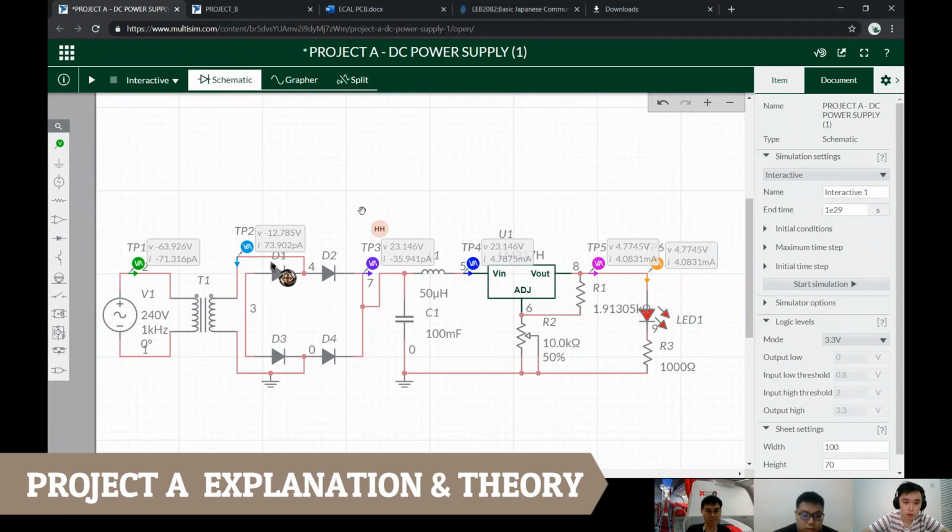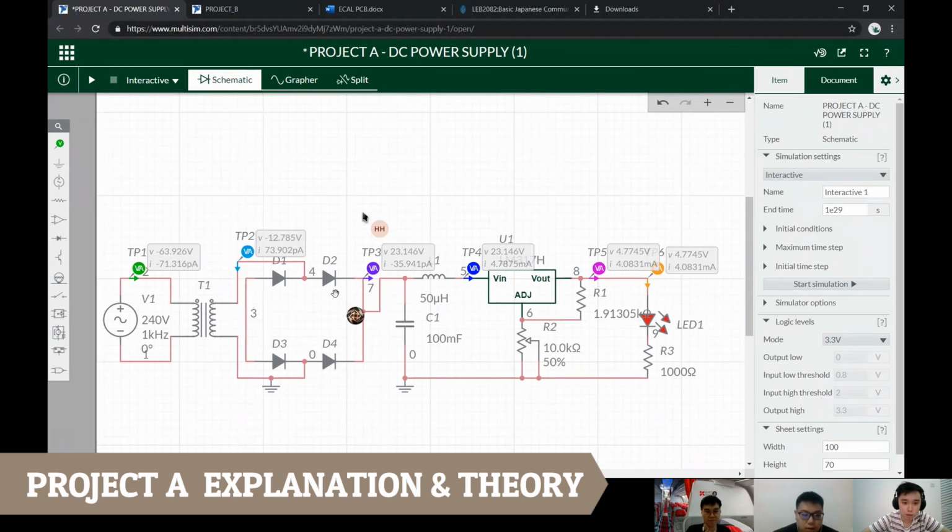Still remaining alternating current. Our second main part is the bridge rectifier. It's a combination of 4 diodes. The bridge rectifier provides the same polarity of output for either polarity of input. For our third main part, for AC converting to DC, this is our filter circuit, a combination of inductor and capacitor. The combination of inductor and capacitor forms a low pass filter circuit. It will pass the DC and low frequency and cut the high frequency signal.